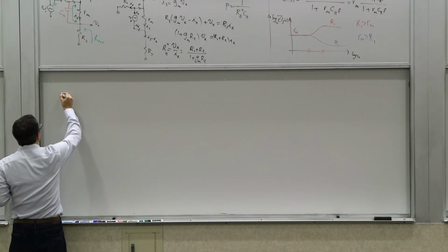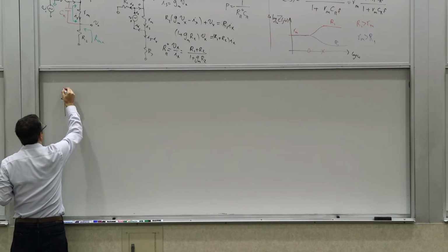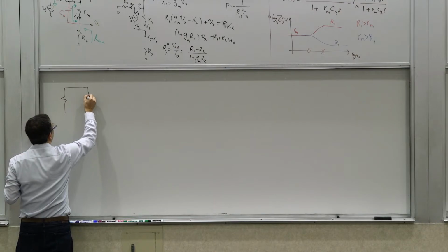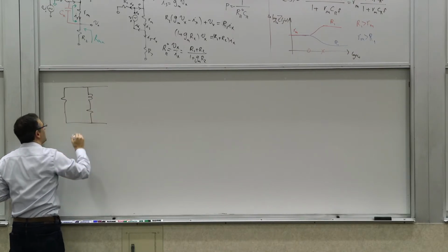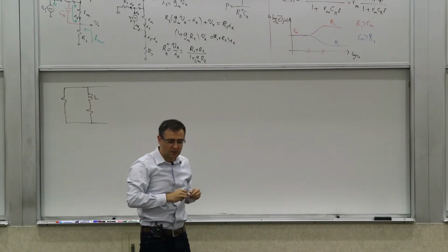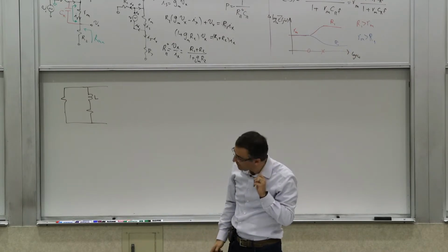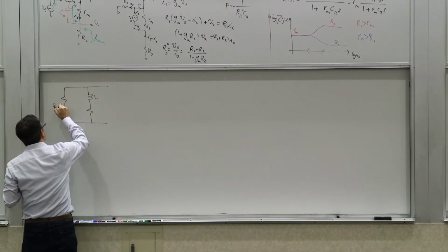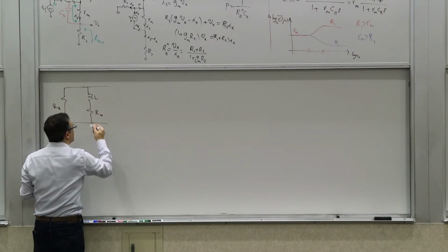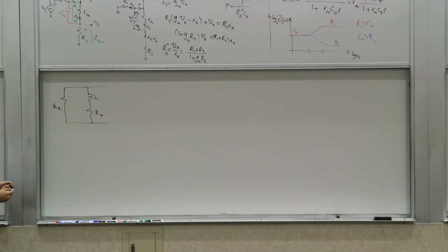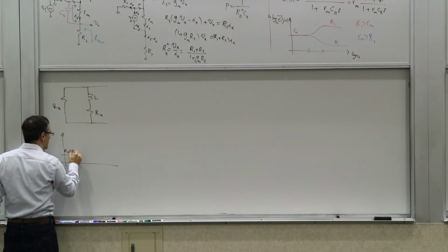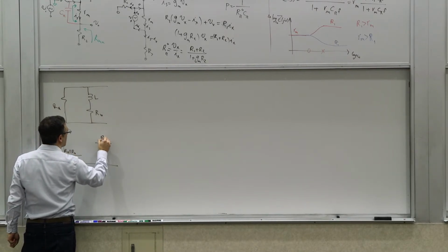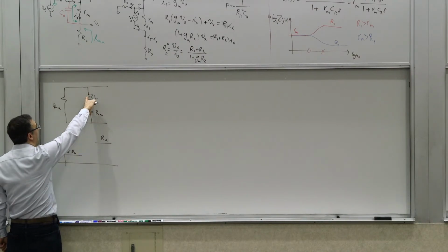So if I take one resistor and then put it in parallel with an inductor and another resistor, what would this transfer function look like? What would this equivalent circuit look like? Let's call this RA and RB. What is this impedance like? It starts at RA parallel RB, right? And then it ends at RA, right? Because at very high frequencies, this becomes open.